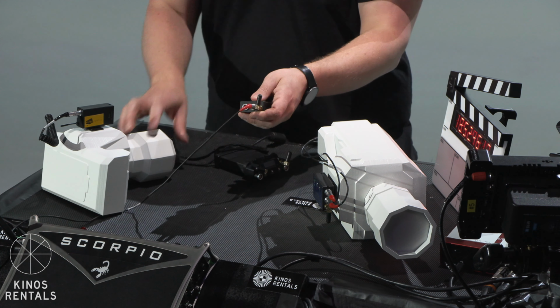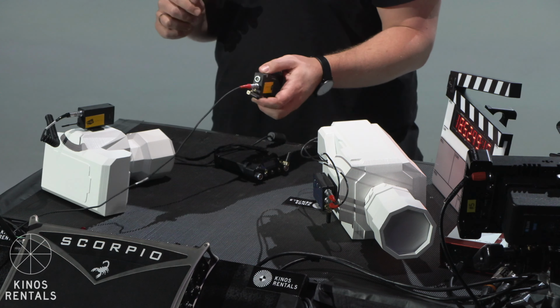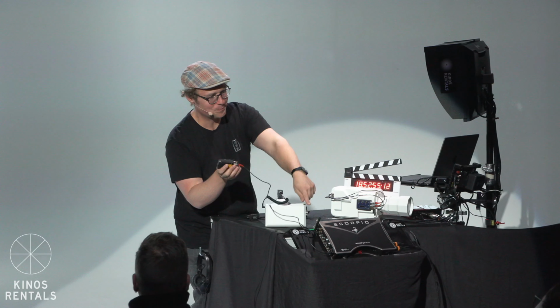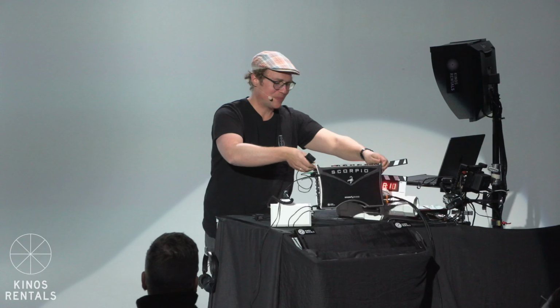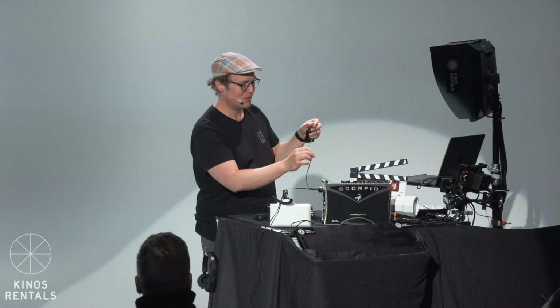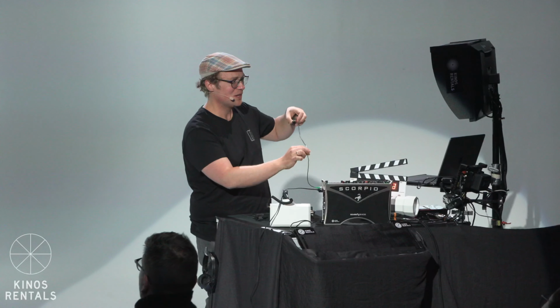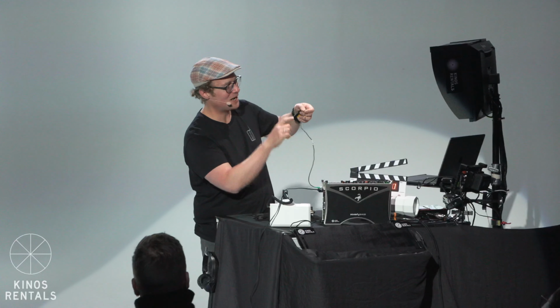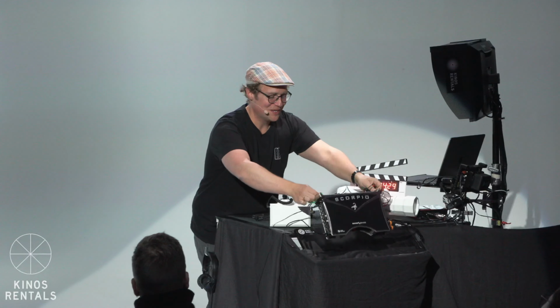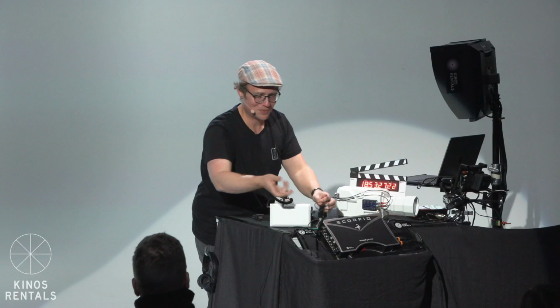Another important thing about cables is to know that timecode has a direction. It's not bidirectional, it's unidirectional. So for example, here at our Scorpio, where we have a LEMO in, and our Lockit has also a LEMO connector, you wouldn't know which one to plug in where. So we have this color-coding here, and also a little arrow on our cables. You can't see it now, but there's an arrow showing the timecode is flowing from this device to that device. That's sometimes also a common mistake that can happen, that the cable is plugged in the wrong way.